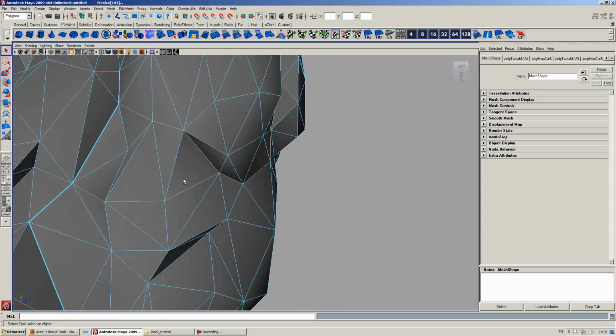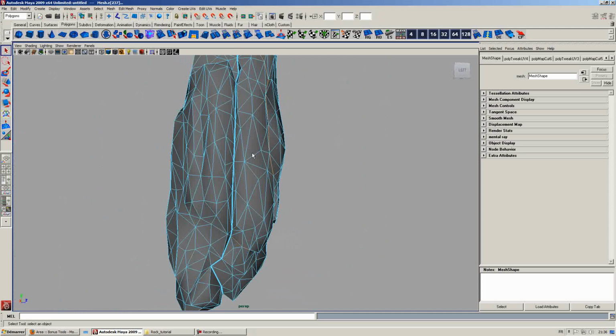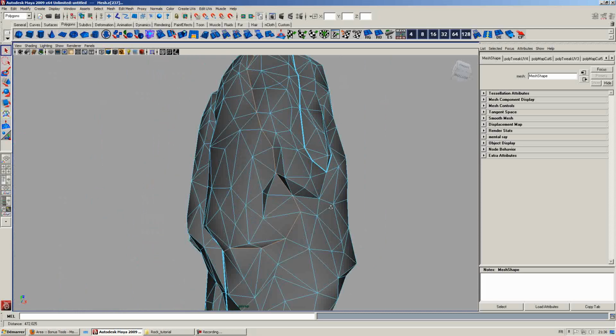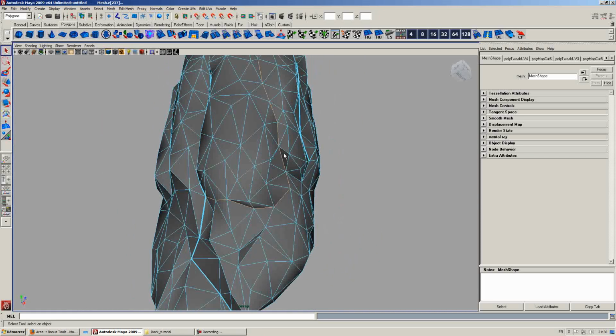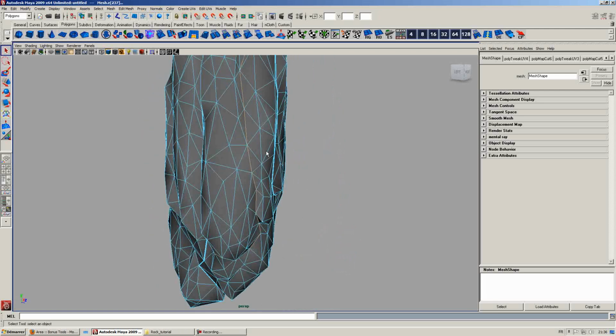Always try to guess the best flow to follow for your UV seams. This is really important, that way you can have proper texturing, and always try to hide and guess where the different parts of your high poly model are linked together.